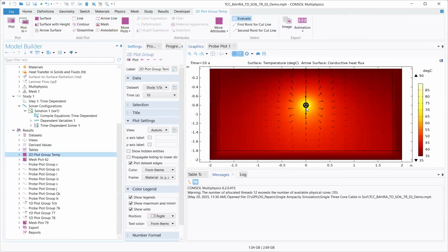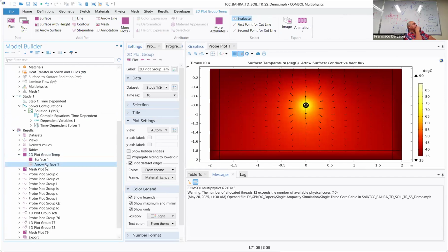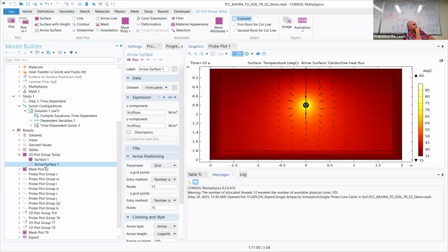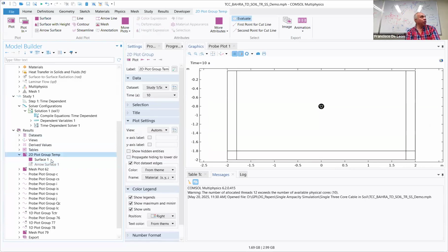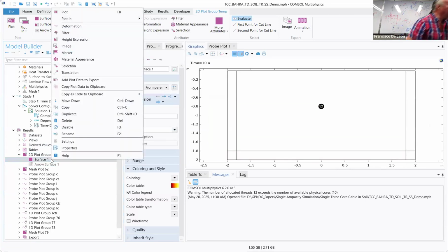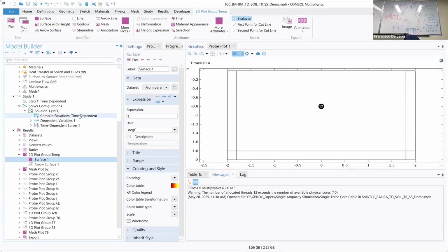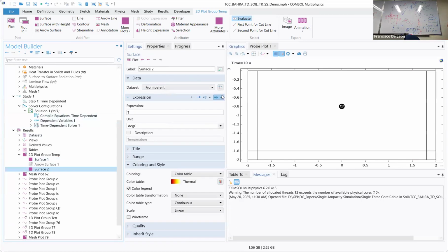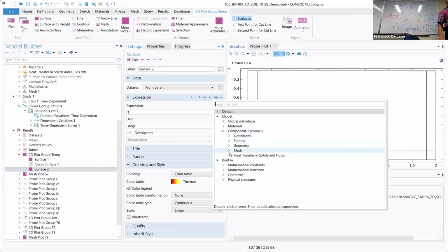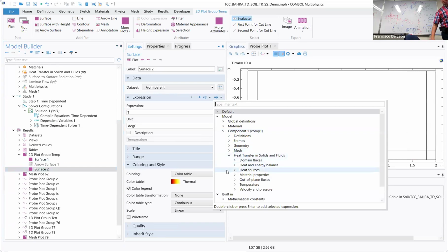Show me, please, the temperature distribution, and if you have the isotherms, remove the arrows and give me the isotherms if you can, please. I can explain this. This is in solid, in ground. It's an underground cable. So the air starts here. Here is air. The rest is the ground. And it's buried about a meter underground, which is the standard.